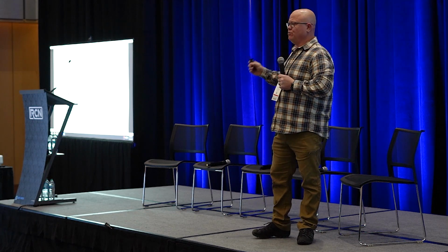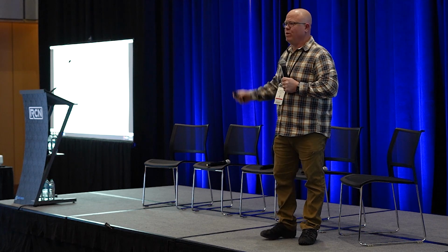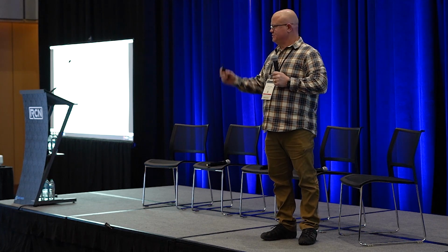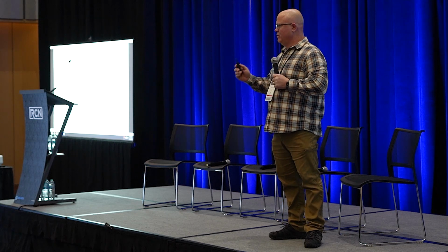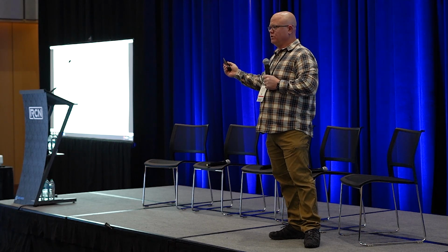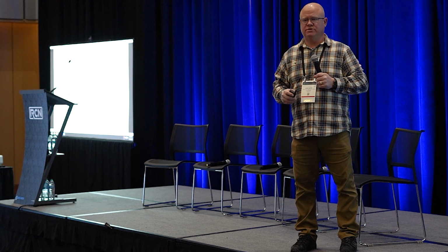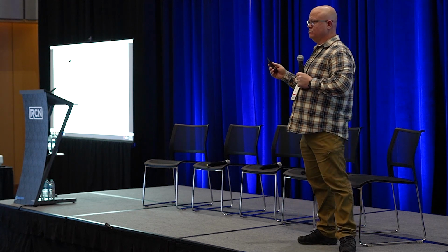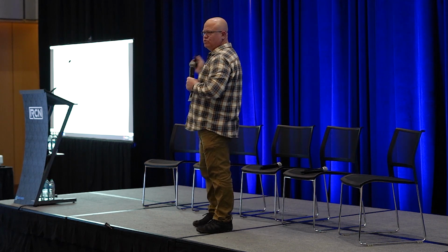You can publish your point clouds to Autodesk Docs, and we can view them in a web browser, okay? That's what I was going to show you today. But you can look at them in a web browser. You can not only look at them in a web browser, but you can pull linear features in a web browser. Not on your local, in a web browser. So if you don't even have Recap Pro on your machine, you can still do this, okay? Because you're logged into Docs, all right? It's a named user login. So you log into Docs just through Google Chrome.